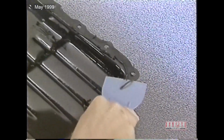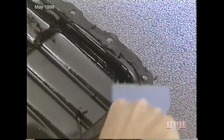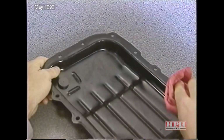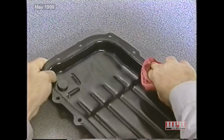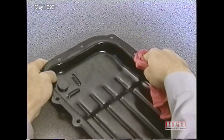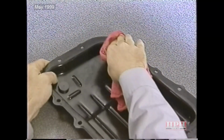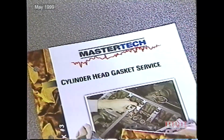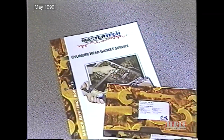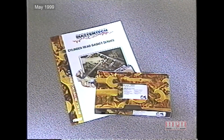Whenever necessary, use a plastic or wood scraper and gasket remover solvent, being careful not to gouge or scratch the sealing surfaces. You can use a cleaner such as Mopar brake and parts cleaner. You want to make sure that the surface is smooth and clean, free of oil and dirt. Also, be sure that you're using a lint-free shop towel. For more information about cleaning aluminum sealing surfaces, refer to the 1999 March MasterTech program, which covered head gasket service.